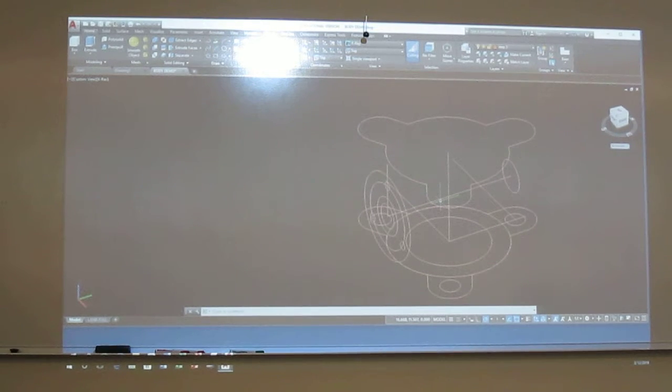So when you move that bottom shape to the top, you can be in the front view and move that. I can be in any view I want to be. To show you, let's go ahead and delete that. It's gone. Now I'll just do a copy command, not 3D copy, just copy. So CO, enter. I'm going to select that, and I'm going to snap it from there to there. It's now in place. So I didn't have to use 3D copy, I didn't have to use 3D rotate on any of this. It's all two-dimensional drawing.